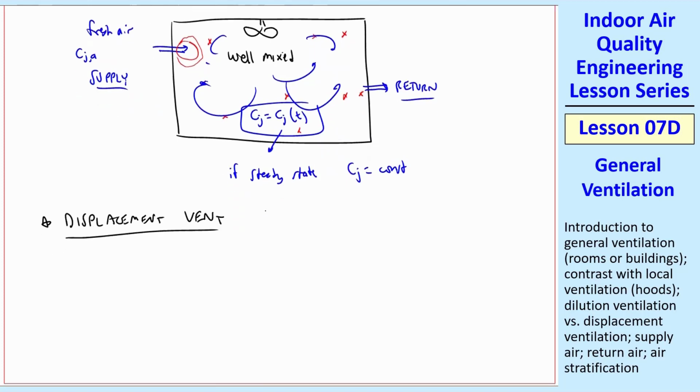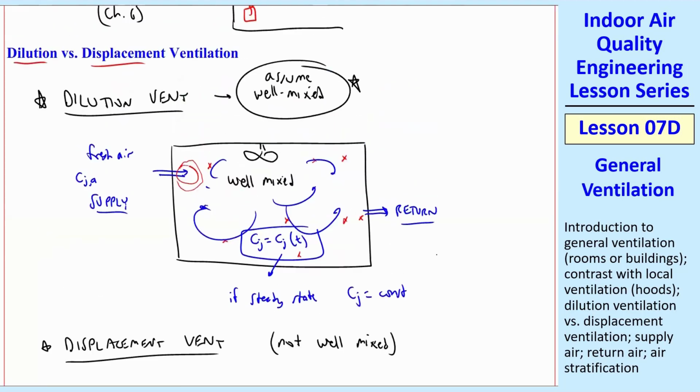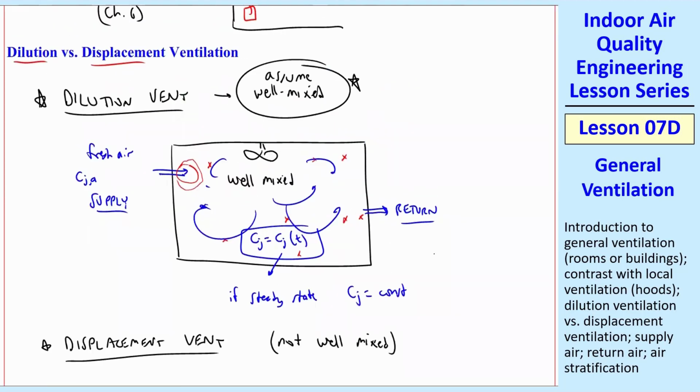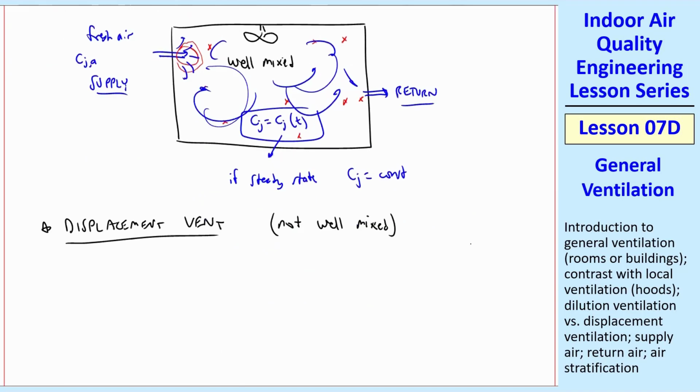And that's a very different animal. The goal is to not be well mixed. Most American homes and businesses, offices want the room to be well mixed. So you may have a ceiling fan, or even if you don't, they design these diffusers on this supply air so that it pushes the air in various directions, and then you're drawing air in other directions, and it's assuming that you're setting up these big eddies, even if you don't have a fan, so that the air is well mixed. Displacement ventilation is the opposite.